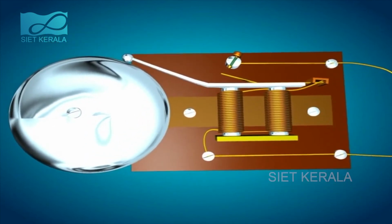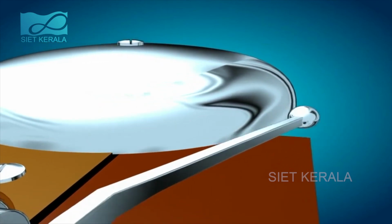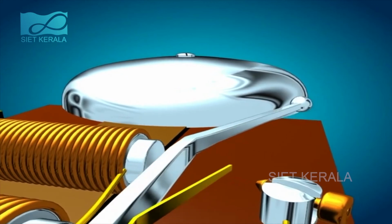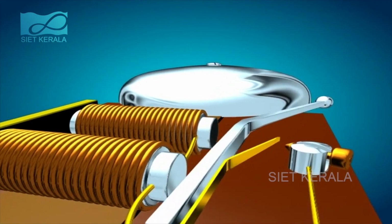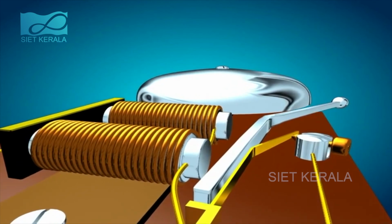Working of an electric bell. When the current is switched on, electricity is passed through the wire wound around a soft iron core. The soft iron core is magnetized and it attracts the iron strip. The hammer fitted with the soft iron strip hits the bell and sound is produced.